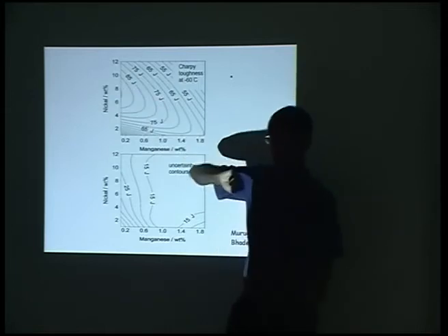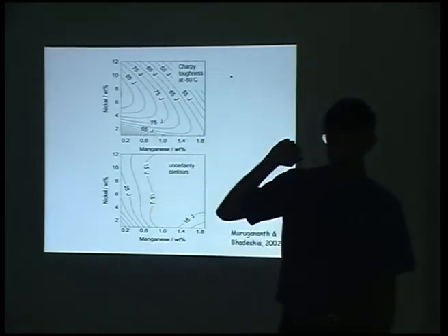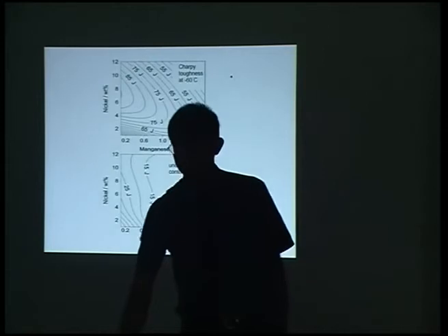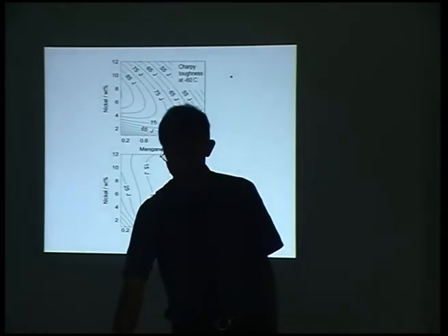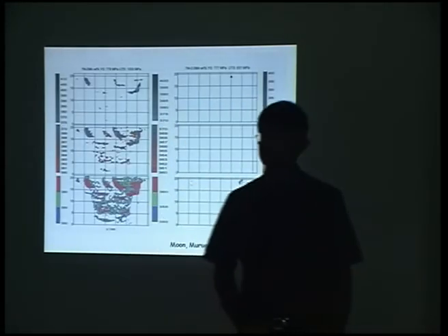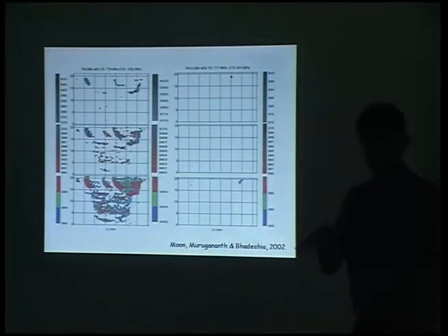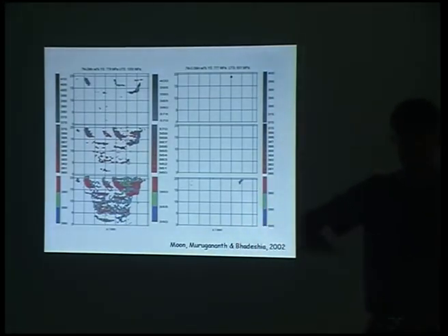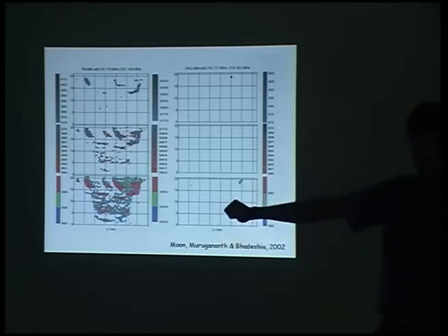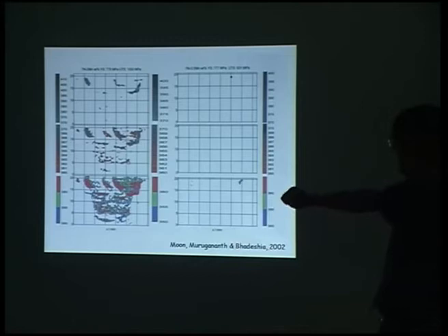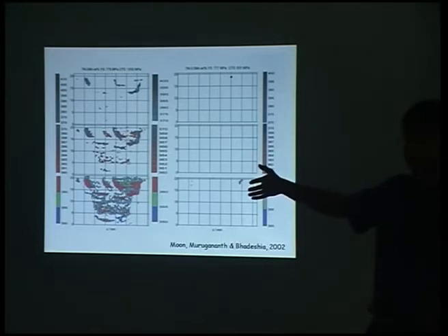Now, of course, this doesn't tell you why this effect works. It just tells you that nickel will work at a low manganese concentration. So we did these experiments. Now you have in this laboratory a hardness tester which maps a complete weld. And these experiments are done using that hardness tester. And what you see here is hardness contours. Notice how remarkably they reflect the microstructure. There's nothing here except hardness being plotted.